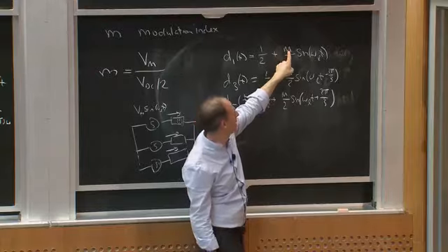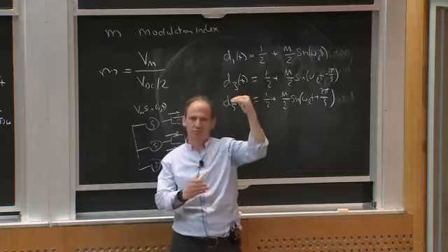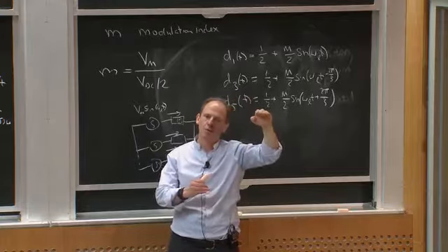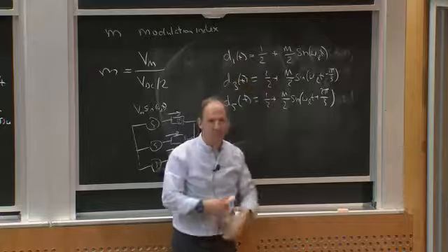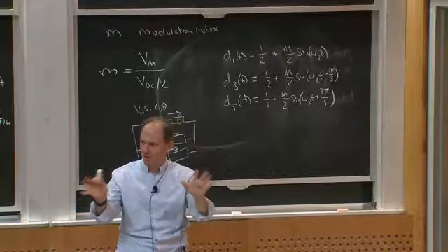Because when m exactly equals 1, the peak of this drives the duty ratio to 1, just touching the top. If I tried to make m 1.5, for some part of the cycle, duty ratio basically saturates at 1, the top switch is on, and I get a bunch of distortion. Is that clear to everybody?